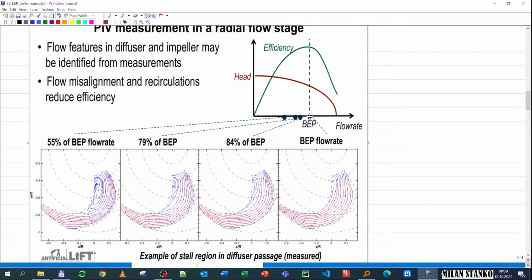So then it flows smoothly through the passage and follows the contours of the passage. But in this case, when you reduce the rate, the velocity of the fluid is not aligned anymore, but is going at an angle. Because of that, you have some detachment of the fluid from the walls, and you create local recirculation places in which you have turbulence and eddies that dissipate energy. And you see here, if you reduce further and further, you have a greater recirculation area.